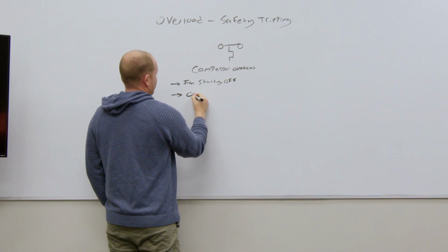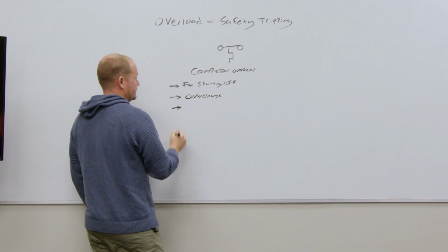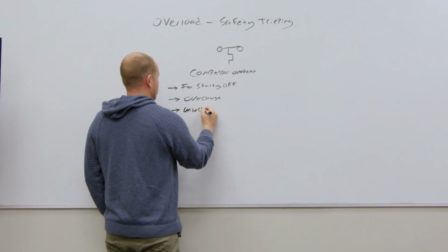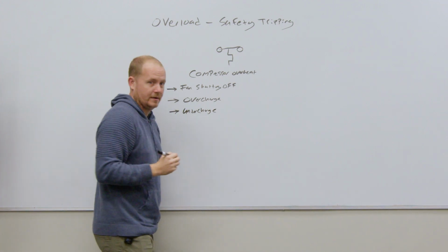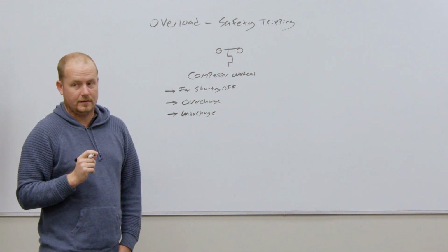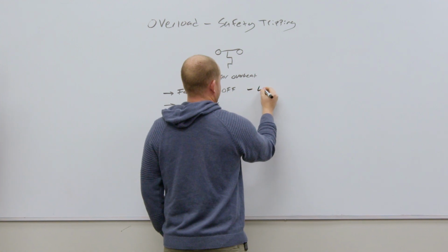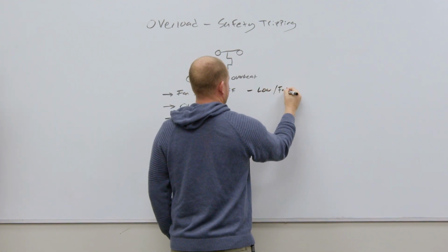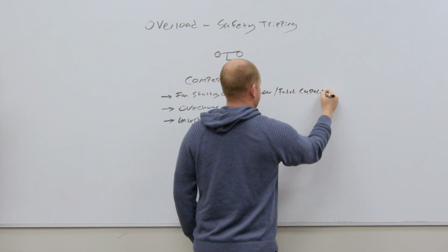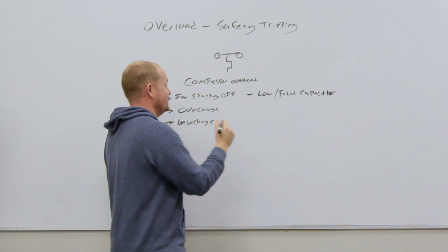Oh, overcharge. Okay. We'll talk about that one. What else? Undercharge. What else? Low or failed capacitor. All right. We could have a low or failed capacitor. Okay. How about the suction service valve is not open. Suction service valve closed. Okay.